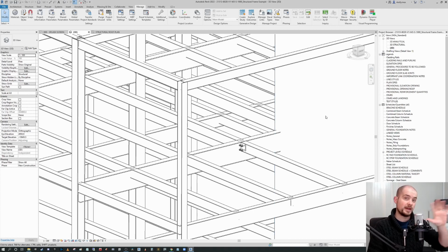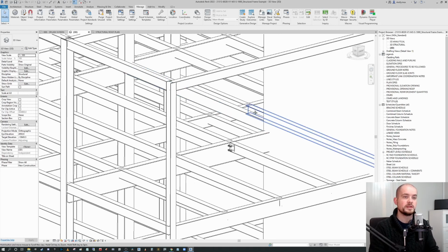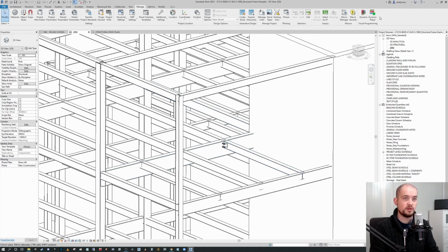So you could actually have a blank file if you wish, with all the connections defined in advance, and then every time you're doing a modeling exercise and you need to generate all your connections en masse, you can literally just point it towards this information rich empty file that's specific for connections, and it will actually generate all the connection rules for you. You can just let the Dynamo script run and you're off to the races. Okay, so now that we've done that, we're going back to our Dynamo player.